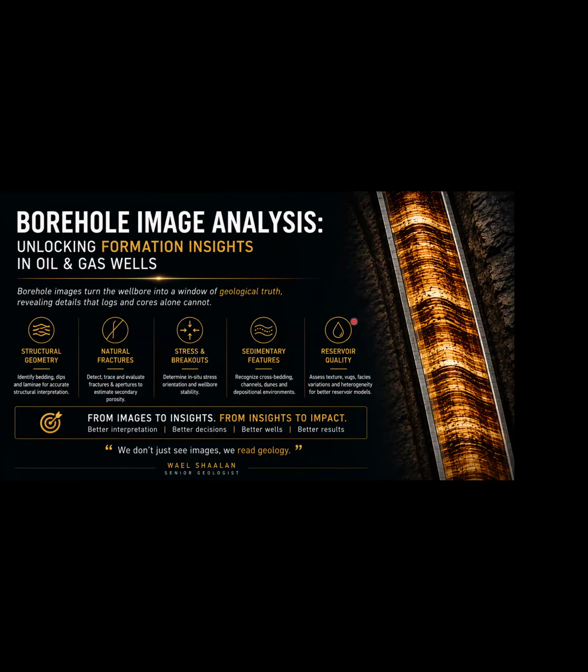And also we get not only geological data, but also mechanical or geomechanical data as well, related to the borehole shape analysis. When we talk about the in situ stresses' impact on the wellbore, especially for the main two failures we have, and they are challenging, especially in deep drilling, which are the breakout and induced fractures.